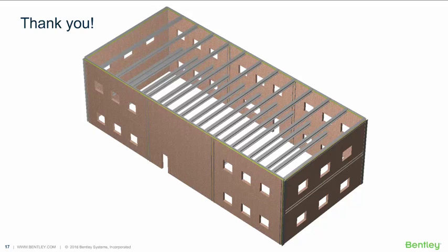There's another question that says, do you have to import the full model from the RAM structural system, or can you just import the lateral model when designing shear walls? It's your choice. If you have completely designed all the gravity system in the RAM structural system, then there's no need to bring the full model. You can just bring the lateral.